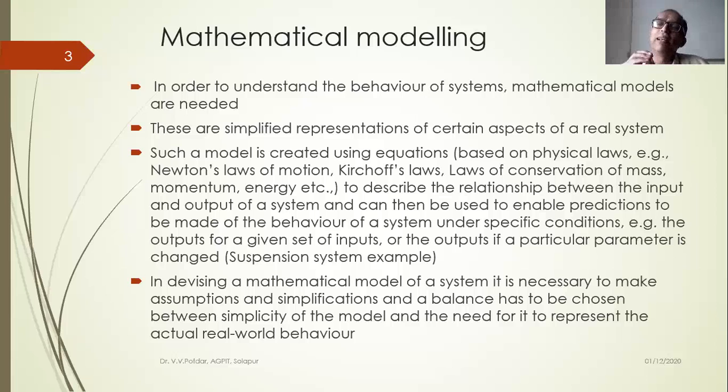I'll be inputting that mathematical equivalent of an impulse force, and I'll solve that equation of motion of this spring mass dashpot system. By using this impulse input function, I'll be able to solve that equation to find out how much will be the displacement transmitted to the rider and pillion rider.